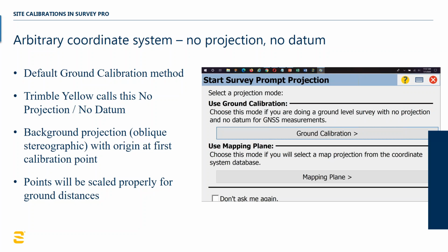So anytime you do an adjustment, you sever your ability to fix rod heights or to recalibrate with additional control points. You've essentially recalculated that coordinate, and we turn it into a stored point, and it's no longer connected to the observations. And that's really the important reason why it's always recommended to do the recalibration or do the adjustment based on the original measurement coordinates, and understanding that using the translate, scale, or rotate from the adjust menu will sever that connection to the observation. Thank you.